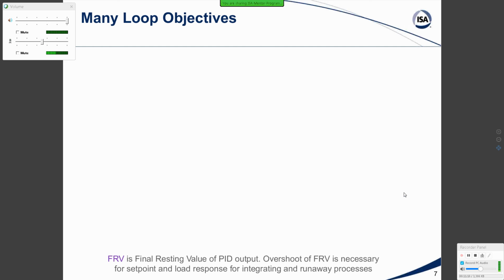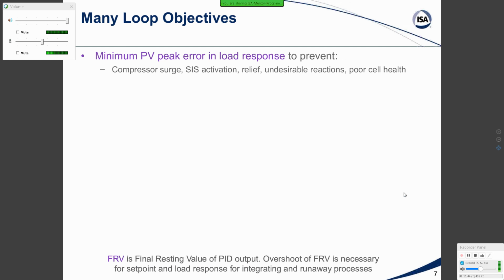And it's very useful, in some cases as a metric, but also if you wanted to calculate the open loop process gain, you can do it in a closed loop fashion by making a set point change and looking at the change in PV once you settle out and dividing it by the change in the PID output, and that can give you the steady state gain. So it has a lot of uses, and in some cases a metric.